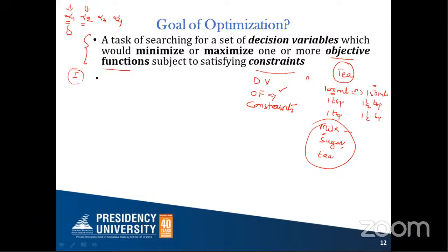I want to control the multi-level inverter. I have to control the inverter at a wide range of modulation index. And while controlling this multi-level inverter, I have to see that it will produce a low percentage of THD according to IEEE 519-1992 harmonic guidelines. That is our objective. We should not control our inverter as we like. There should be some IEC guidelines or IEEE guidelines. According to that, we have to control this inverter. Let us say if I want to control this inverter, I should produce a low percentage THD, let us say less than 5%.